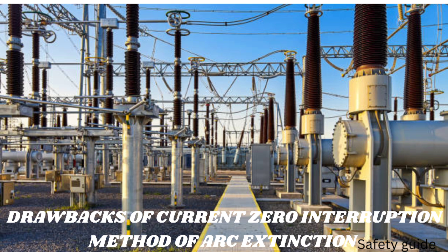2. Dependence on current zero crossing. The current zero interruption method relies on the natural zero crossing point of the AC waveform, which may not always occur at the same point in time. 3. Potential for reignition. If the circuit breaker contacts do not withstand the recovery voltage, there is a risk of arc reignition, which can lead to further damage and safety issues.